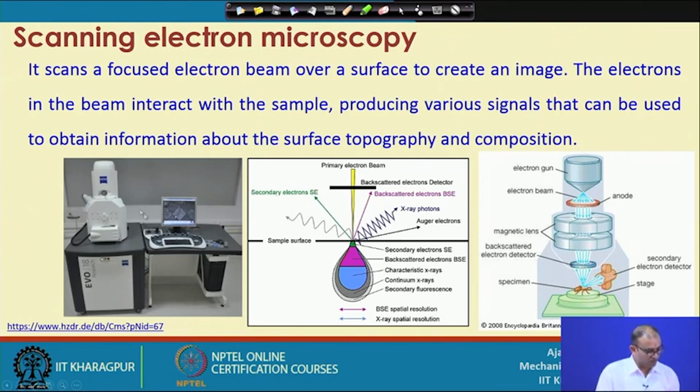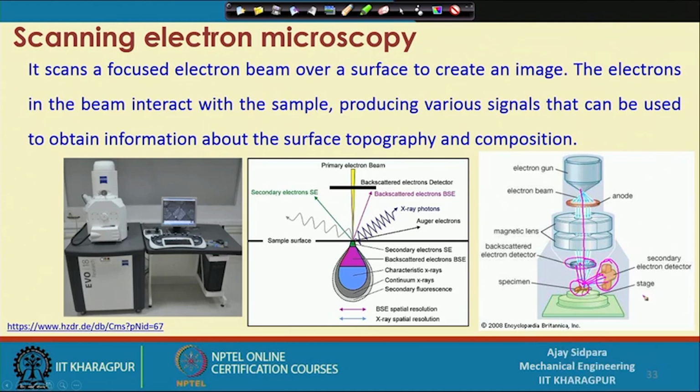So, this is the full photograph of that part surface, and this is the initial wave. Now, when the electron beam passes through here and interacts with the surface, it generates secondary electrons. There is a detector available which will capture these secondary electrons, and there is a backscatter electron detector which will capture the backscatter also. If you see the more inside view of this, this is the surface and these are the secondary electrons here, backscatter is here.